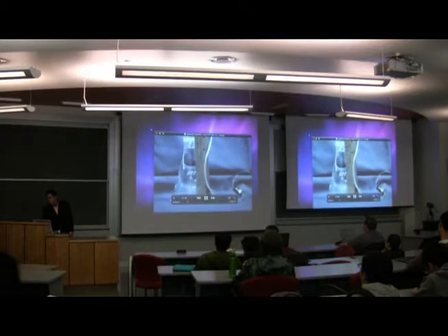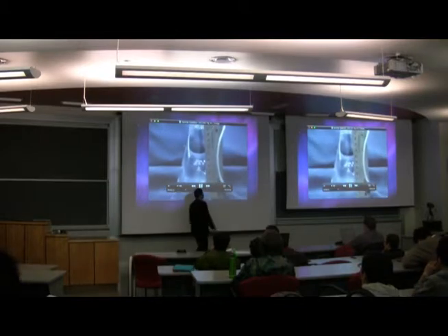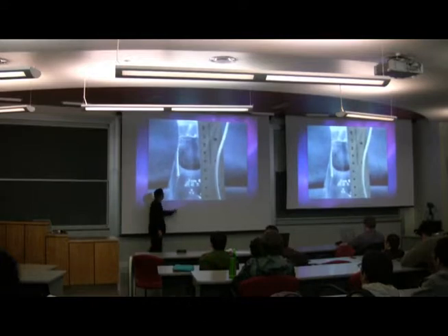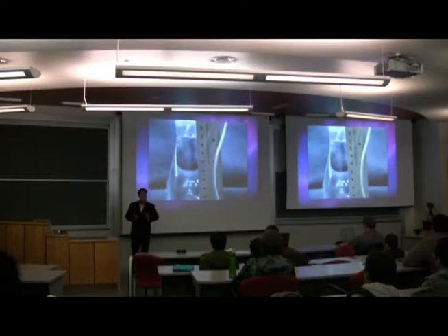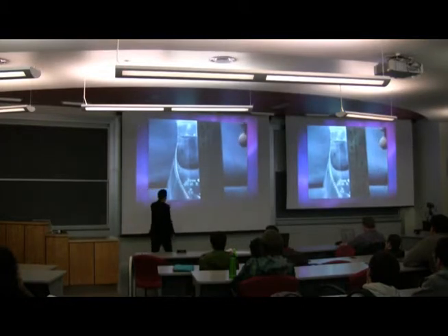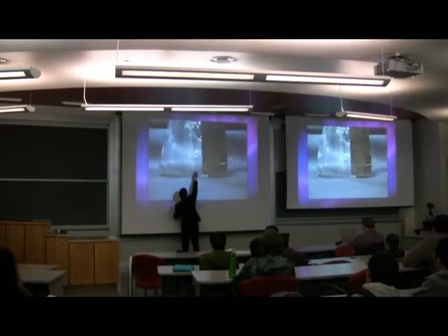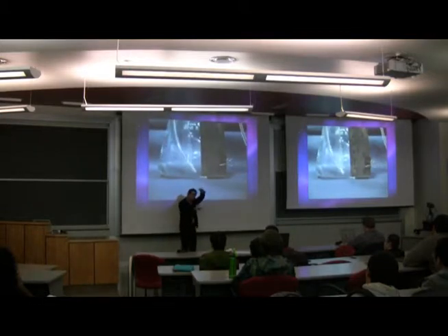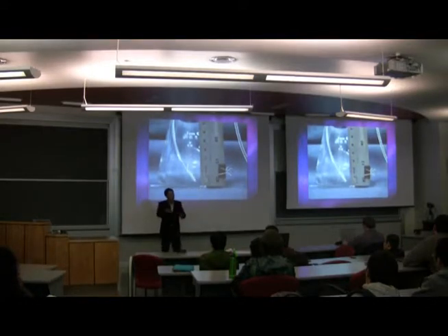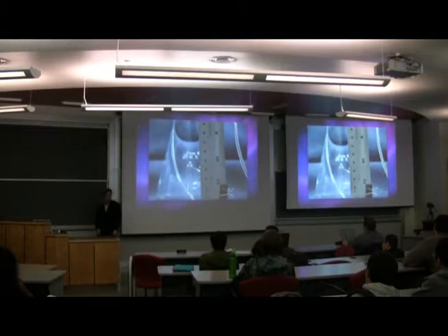So you have this little pump over there, and it is pushing the air, and air comes in through this one and then comes out of the water, which means this pressure is high enough to overcome the tension at the water, right? And also the height from the end of this tube to the water surface is imposing some pressure, right? So this pump is overcoming that much pressure plus water tension and generating flows.